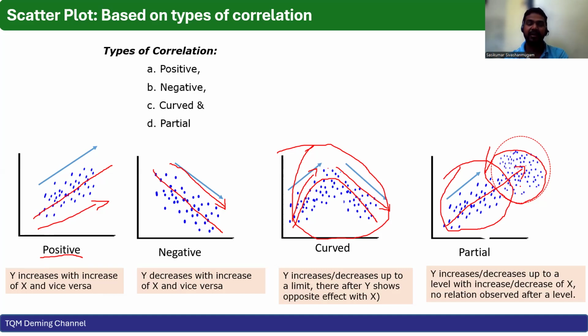It is very rare, but when we see this type of data, it clearly indicates a data error, new manpower, or calibration error. Somewhat external noise is there. So we want to replicate the values and calibrate our instrument first. It clearly indicates some error in the process, not a process deviation. So we can see this type of data is also noise in the process. So these are the four very important correlation studies of the scatter diagram, and how we need to read them from the readings.